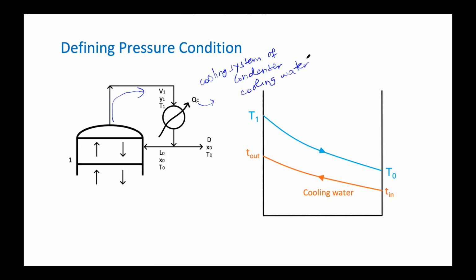You can get the cooling water from the river, for example, if your chemical plant is near the river, or from the sea, if your chemical plant is very close to the sea. That's why so many chemical plants are near the sea, because we can get basically unlimited water, and some of it is used for cooling water. Now, for the cooling water, let's say this is 25 degrees Celsius. There is a maximum for how much the cooling water can be heated up. Sometimes it's only like 9 or 10. Correct me if I'm wrong, but you can talk to Professor Harry or Pak Walmiki if you want to ask about the utility system. I need to remember as well, 25 degrees.